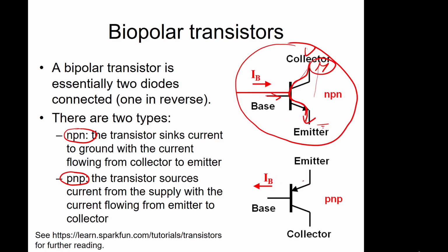For a PNP, it's a similar arrangement. So you've got the voltage up here, the ground on this side. This time, the current in the base is in this direction. So you have current flowing through here. Some goes that way and the rest goes down to the collector. And in this case, you would attach your motor to the ground side of this connection. So these are known as current sources because the source of the current is coming through here to the motor.